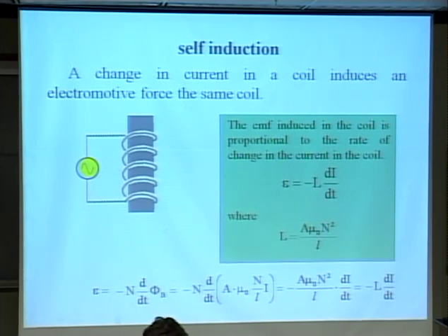Yeah, because indeed, magnetic field produced inside of the core is now greater than when we had an empty solenoid. By what factor? It would be good to remember 1 plus susceptibility of the core. So the inductance will have a factor which involves susceptibility of the core.